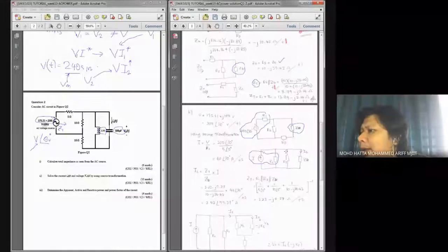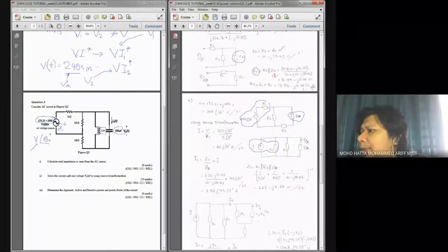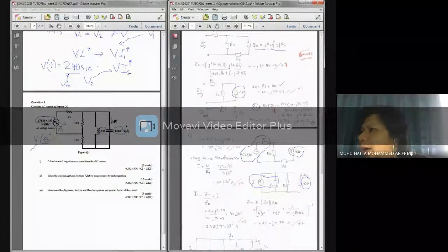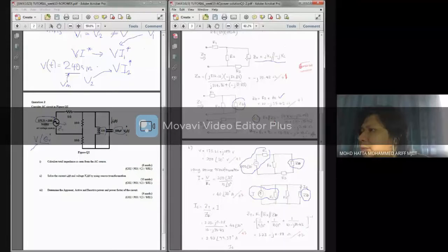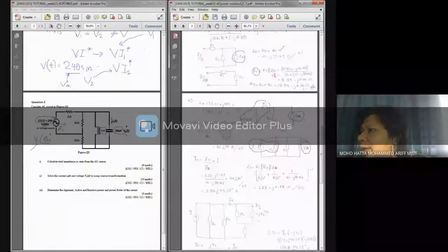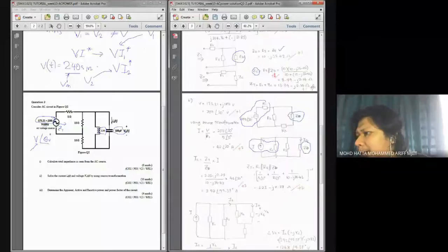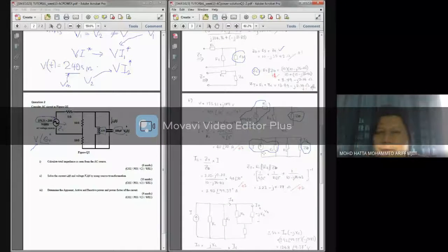And if you look at ZB, okay, ZB is the combination of ZA and R3. So these two are connected in series. You need to combine that one first, and at the end you will end up with 3 connected elements in parallel with your current that you transform from voltage into current source.